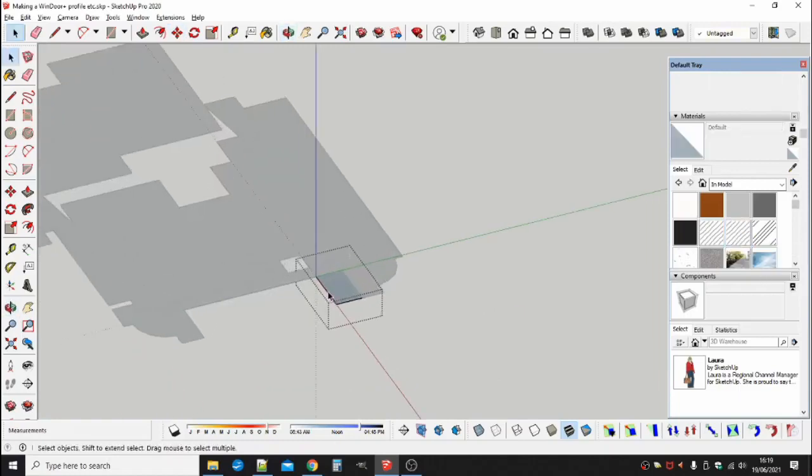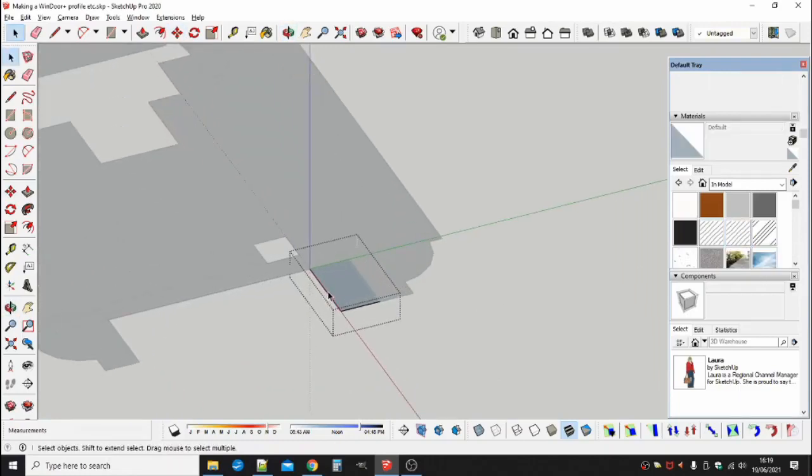Check that its origin is bottom left. The entire rectangle should be in the positive quadrant of the local drawing axis. That is, green axis to the left and red axis to the bottom of the rectangle. SketchUp will already have placed it there if you simply draw the original rectangle in the SketchUp model as done here, double click it and group it.